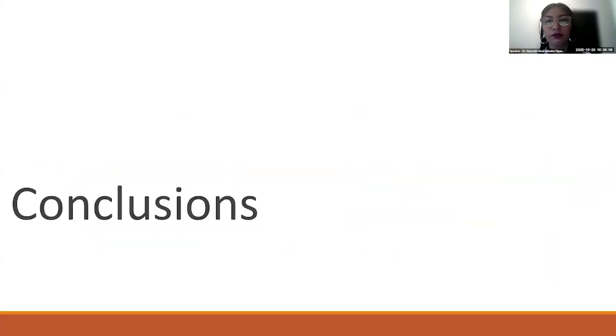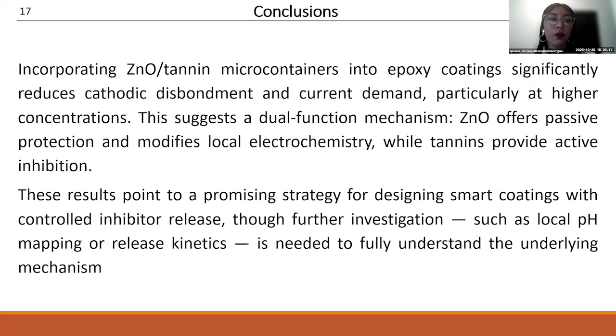release of the inhibitor. So to conclude, incorporating zinc oxide and tannin microcontainers into an epoxy coating significantly reduces the cathodic disbondment and current demand, particularly at high concentrations. This suggests a dual function mechanism where zinc oxide offers passive protection and modifies the local chemistry, while tannins provide active inhibition.